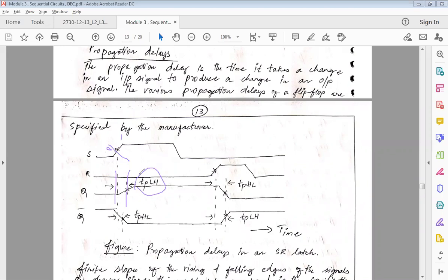Yes, sir. Because these are all a train of values, a train of pulses, I can actually take this at any point of time. It's not that for the chain you should just cut at the first end or at the last end. Any link you cut, the chain is disconnected, right? So this is a chain of values. So at any point I can mark and take it. This difference that you see here is actually called your propagation delay. So much of delay is there when compared to my input and output values. Understood, right?